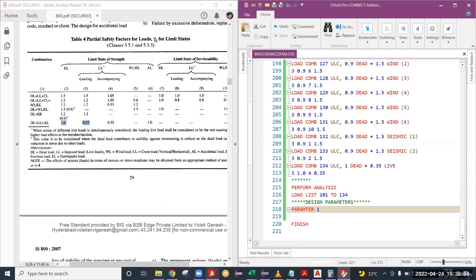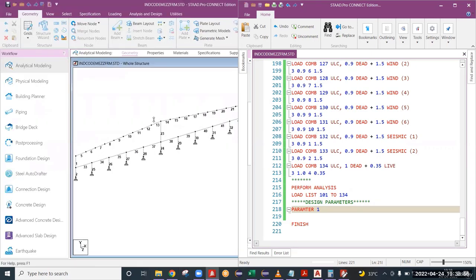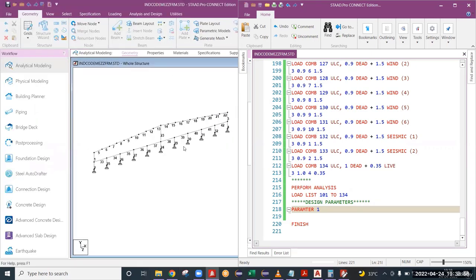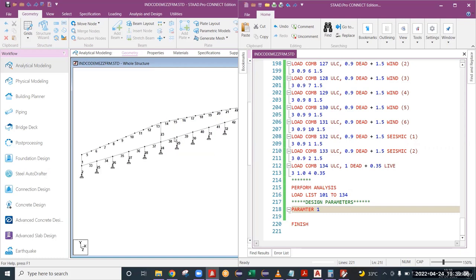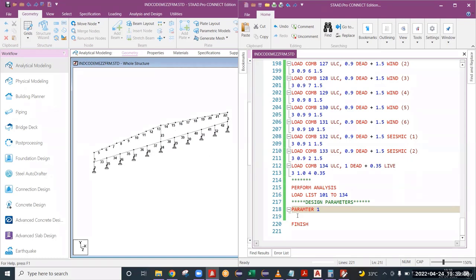Actually, in PEB generally we go with built up sections. A built up section is nothing but different plates connected to form web and flanges. That is a built up section in common terms. A hot roll section is directly molded in a mold. You want to check which is economical.